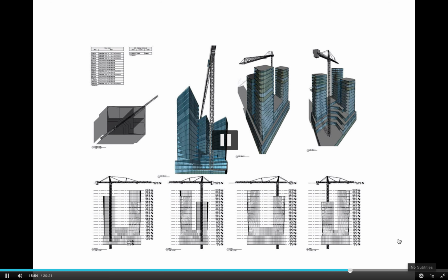And what you usually have are plans for your picks, which member of the structural steel frame, and it's put on kind of like a schedule. So when your forces are loading the next member to be erected, it's done in a very organized manner. They know which one is next. It's labeled as such. They put it in position, and it goes up with the crane. And then with every number of members that get installed, you also know which is the last member that gets installed before you have to jump or jack your crane again.